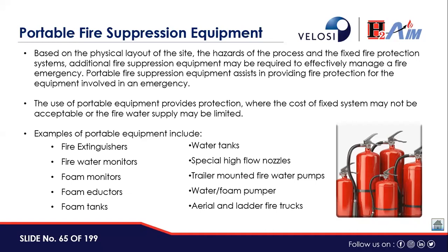Next question. How to classify the size of the fire and how to compute the number of fire extinguishers available to mitigate the fire, considering there is an automated CO2 system also. See, CO2 system is for the closed areas, substations, and control rooms. However, for the other fires where you're providing fire hydrants, hoses, or the sprinkler system, that depends on the process area, total surface area, the kind of fire which may occur, what kind of fire density you need to spray, and what's the coverage area of each hydrant, and then accordingly the number of hydrants and their water demand requirements are established.